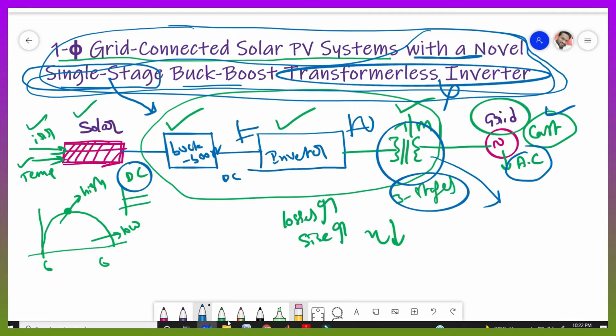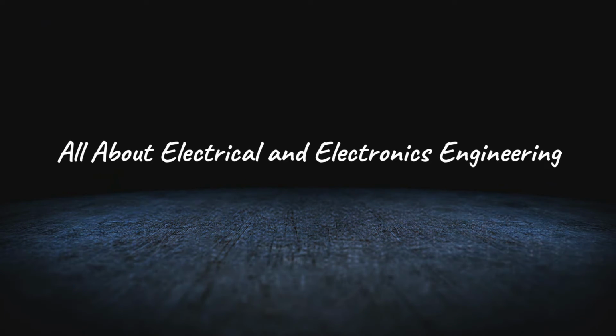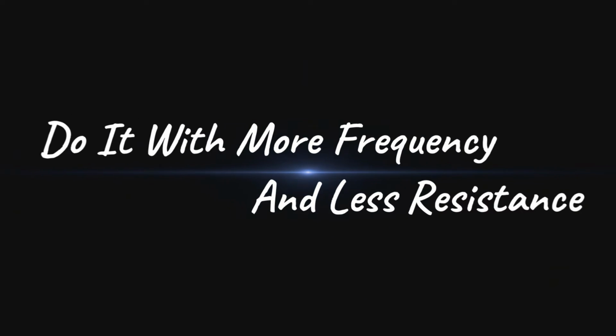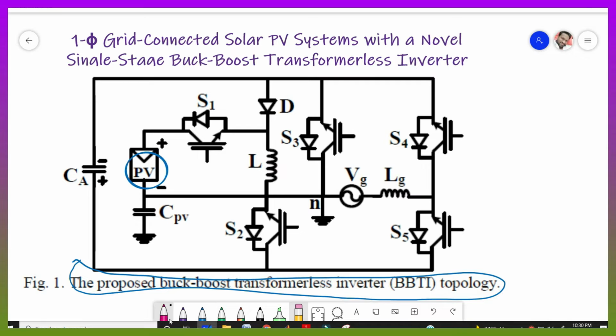Now let's look into our circuit. This is our proposed buck boost transformerless inverter. In this circuit, here we are taking the solar power and here we are taking the grid. And this PV source, nothing but the solar source, shares a common ground with the grid, so that it can eliminate the leakage currents.